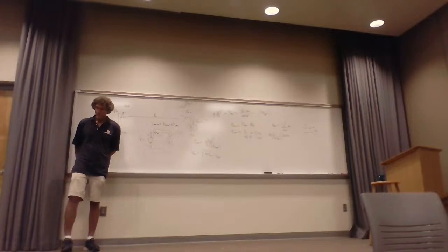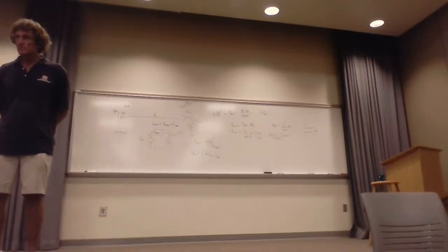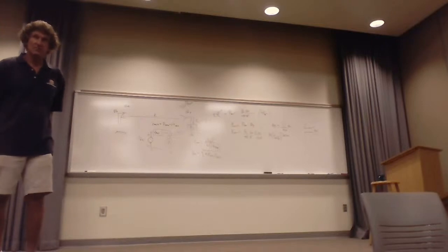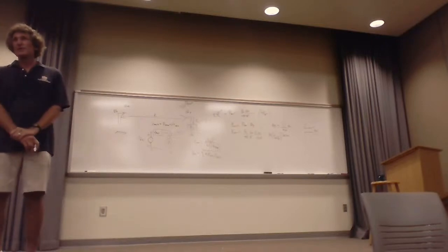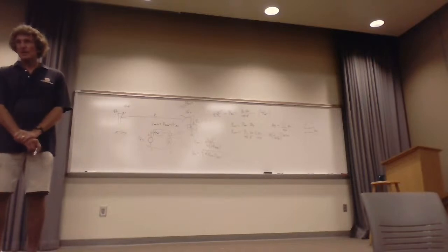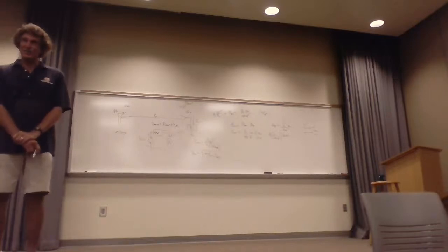So if, for example, it's a half wave, that Z antenna would just be your 73.2 plus j 42.5. You've got to add the j, unless I say it's cut down to 0.485 lambda. Another thing you guys should know, I expect you to know the 73.2 ohms. And remember, we covered monopole too, right? Just have that. Monopole, yeah, that's right. Directivity doubles, resistance is half.